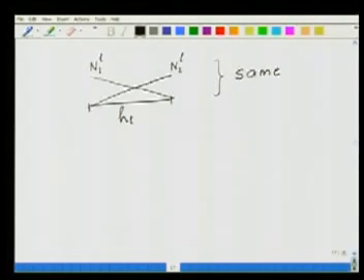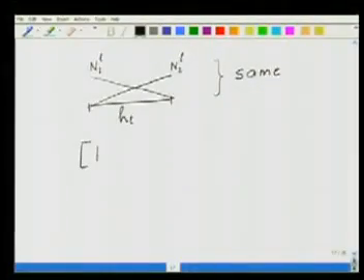So, using this approach that we have outlined for this problem, very easily we can form the stiffness matrix and the load vector for a mesh with any number of elements, with either uniform meshing or non-uniform meshing. Once we do that, we can form the global matrices K and F, and solve.